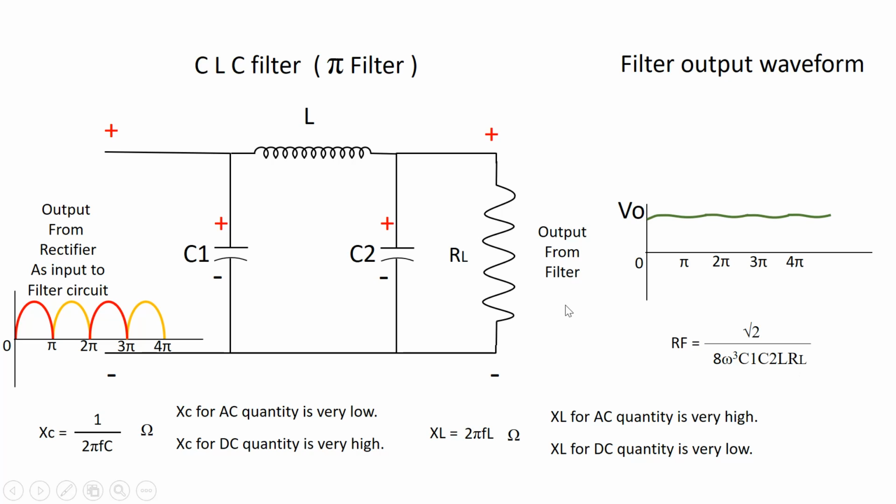The advantage of this filter circuit is that it has a superior filtering characteristic, but the voltage regulation characteristics of both filter circuits are poor. These CLC or pi filters are suitable for work in communication networks, wherein the signals are regenerated at the receiving end.